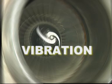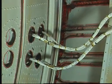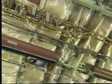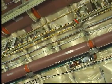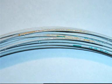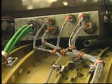Vibration can have unwanted effects on the wiring installation. Areas where there is high vibration tend to accelerate degradation over time, resulting in chattering contacts and intermittent symptoms. High vibration can also cause tie wraps or string ties to damage insulation. For example, two adjacent wires, if not separated by a spacer, may be fully stripped and a short circuit may occur. Special attention should be paid to feeders, adjacent wires and connectors.